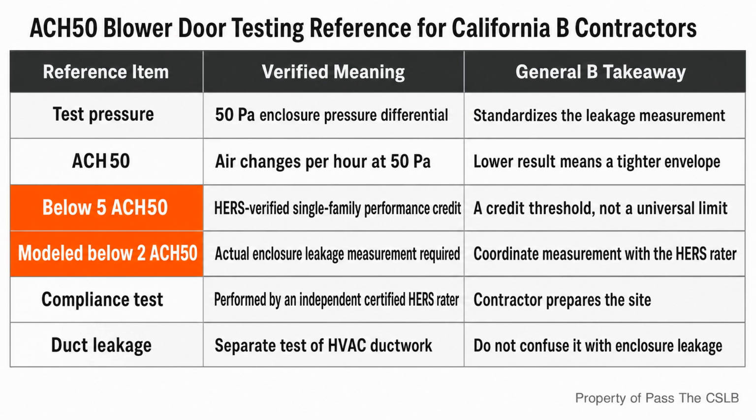The repair search should be systematic. Start with the largest likely connections to unconditioned space. Check newly created trade penetrations, open chases, attic and crawl space transitions, plate joints, electrical boxes, door and window perimeters, and fixtures that interrupt insulated ceilings. Complete suitable repairs while access remains, then coordinate any required retest.